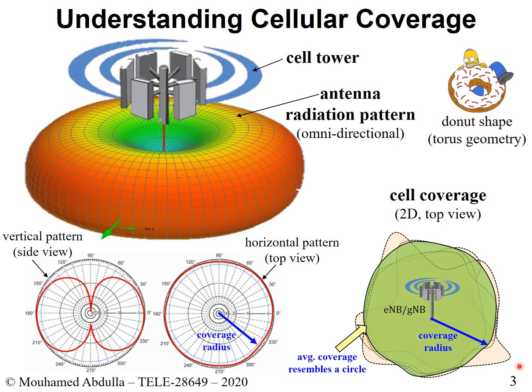And if you're interested, you could also see the coverage radius here and the coverage radius here. Now, mind you that these two coverage radiuses are the same, but these two are not necessarily the same. This coverage radius is in a situation where you're only looking at the radiation from your antenna, and you're assuming that it's a flat area. There's no obstacles, no buildings, there's nothing. Whereas this is the coverage radius while taking into account the different obstacles that you have, and it's an average among them. So just be mindful of it.